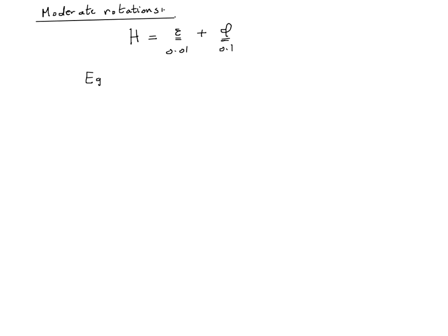we'll find that Green's strain is the symmetric part of the displacement gradient, which is epsilon, plus 1/2 H transpose H. Epsilon transpose is actually epsilon, and phi transpose is minus phi, because phi is skew-symmetric and epsilon is symmetric.